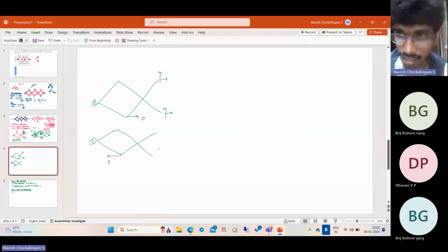And so what do we expect? You have just reversed the load, which means these things have to change, right? So this has to be downwards and this has to be leftwards. So these are consistent. The verticals, and if you put them together, you should get 0 internal forces. That is the other condition, right? So from the condition of anti-symmetry, you see that the internal forces have to flip their sign in these two, but these two are parts of the same structure. Join them together, they must have the same. The internal forces must vanish.